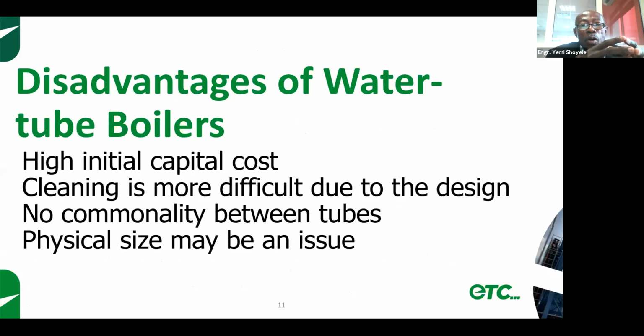High initial capital cost. Well, we say it's a disadvantage, but honestly, if you need a water tube boiler, you got to go for a water tube boiler. Now, cleaning is more difficult due to the design. If you need to clean water tube boilers, in all cases you have to go inside. We'll talk about going inside the boiler and the safety precautions in the coming slides.